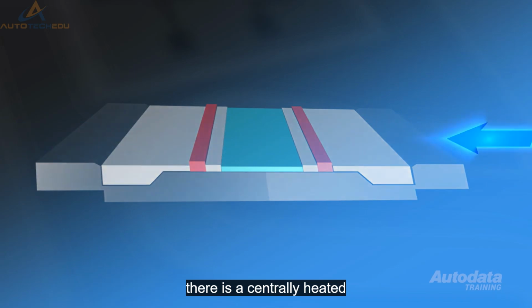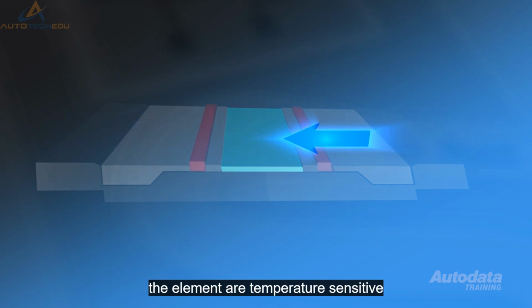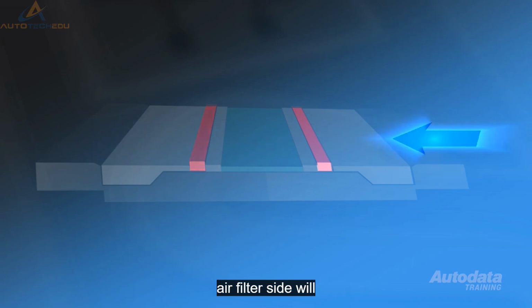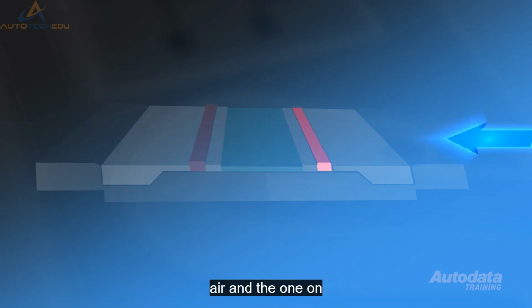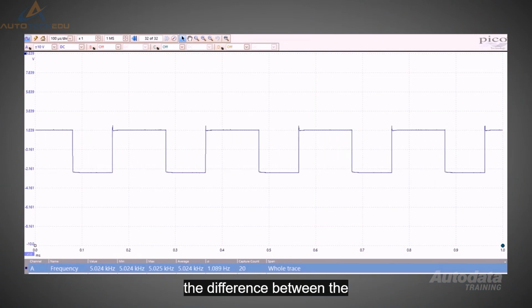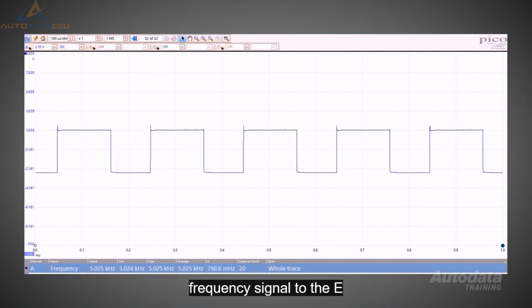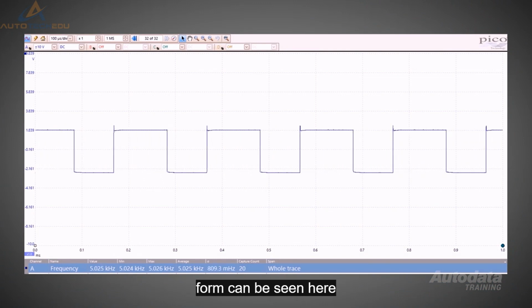There is a centrally heated film or metallic grid type element. On either side of the element are temperature-sensitive resistors. The resistor on the air filter side will be cooled by the incoming air, and the one on the engine side will be heated by the air passing over the element. The difference between the two is measured and relayed as a square wave digital frequency signal to the ECM. A sample waveform can be seen here.